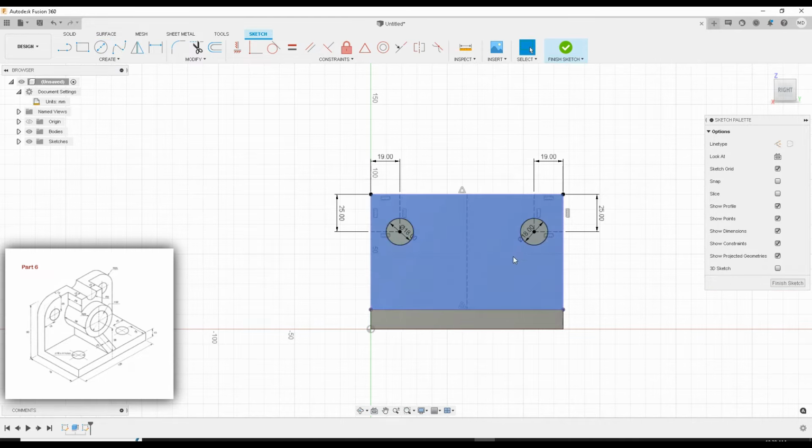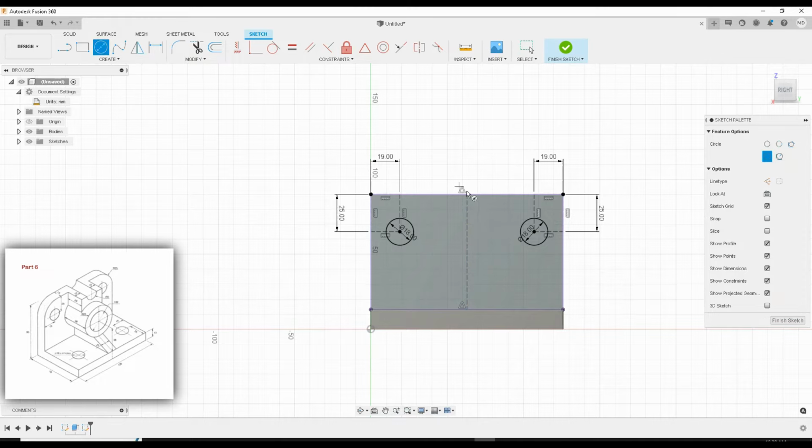Okay, now let's see, what will be the next step? All right, so let's do the top. You probably see that slot there is like a radius slot, a half diameter slot. It's 9 millimeters, which is the radius of 18, so the diameter will be 18, radius 9. So right at that midpoint I drew there, we want to do create center diameter circle, click right on it, and we're going to type in 18.